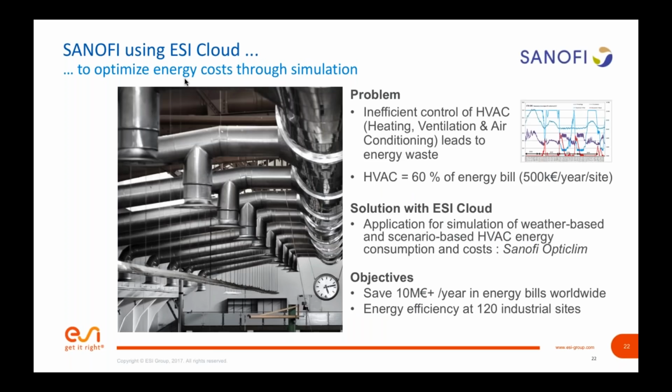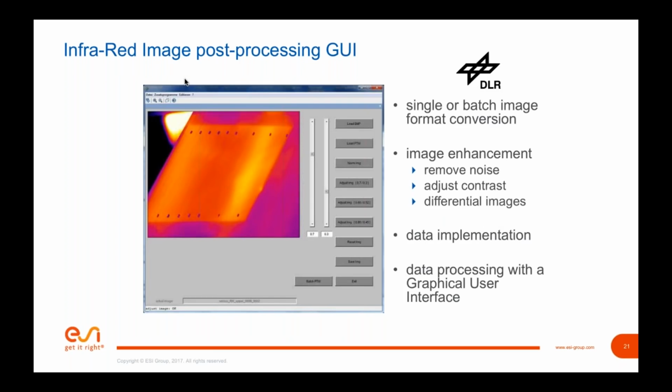There are also some other departments from the German Aerospace Center that are doing some flow cone analysis. They put some flow cones on the wings, they fly, and they look at the behavior of the flow cones in order to identify the turbulences on the wing, in order to give those elements back to Dassault or Airbus to iterate on the design.